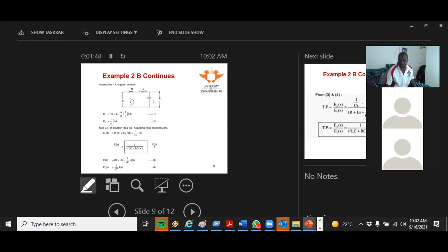Right. So now we have the same circuit, just a copy of that one. But from the word go, we're going to use the transfer function. So Z in, as the equation is there, we convert it into the Laplace transform.